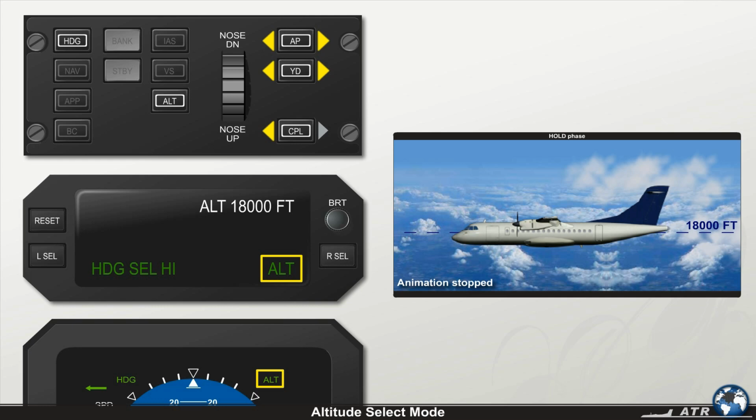If the altimeter setting is changed on the coupled side once the Altitude Hold mode is active, the autopilot will automatically correct the aircraft altitude to the altitude set on the ADU, based on the new altimeter setting. Note that a glide slope capture during any of the three phases will override the altitude mode.